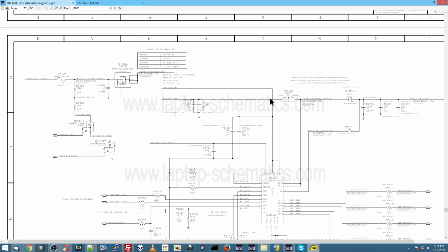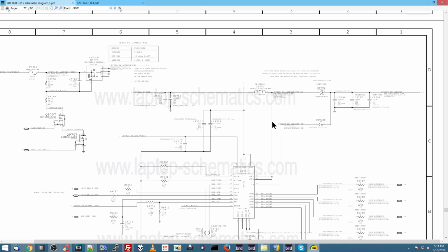And then it's going to come down here and go through this inductor. Right after this inductor, there's a line between here and this chip. And over here it says SW, which stands for switch. This chip is going to switch this voltage, this 12 volts coming through the circuit, from here to ground really, really quickly. Now, this is going to be kind of like stopping short in a car.